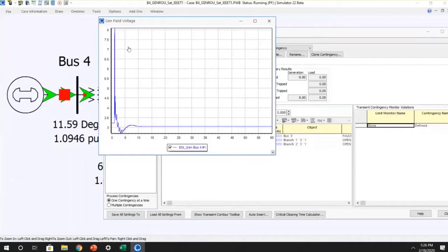So now we've got the high gain, but we also stabilize our response. Whether you want that high gain, we took off our limits on our VR, so maybe it can't really do that. The field voltage is going rather high to do this, but we do get quick response now. So we've got a high gain, we've stabilized it, and maybe it's what we want, maybe it's not.